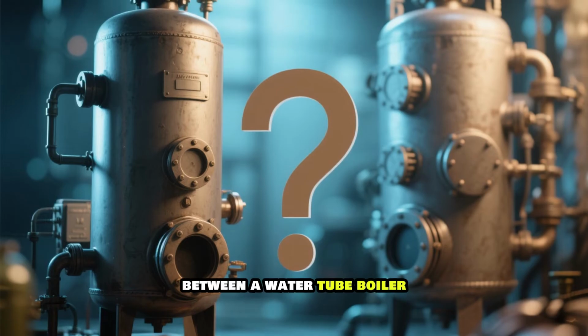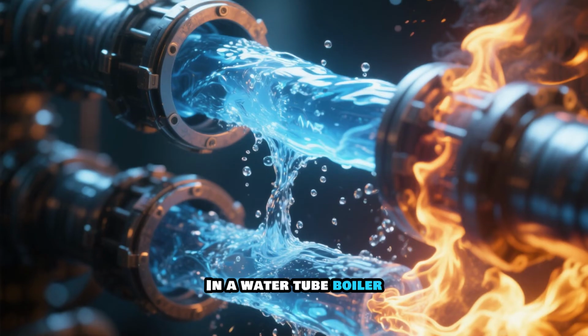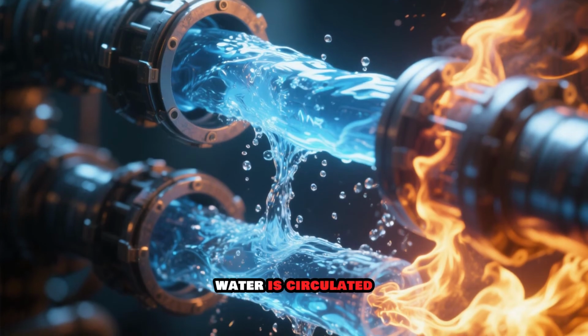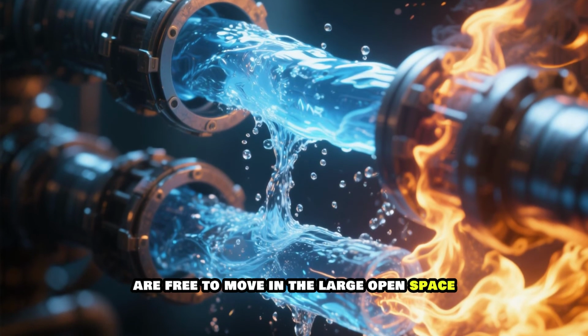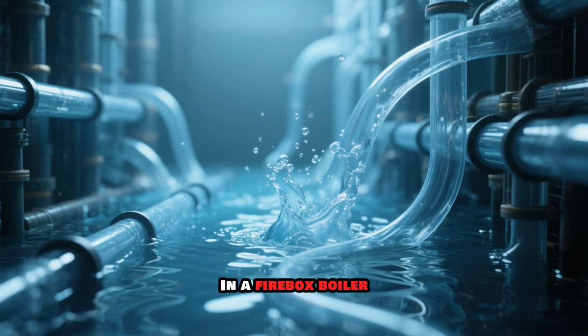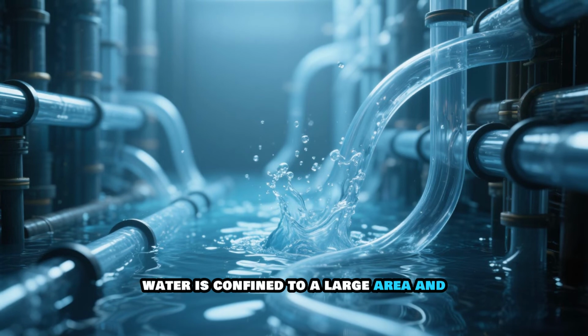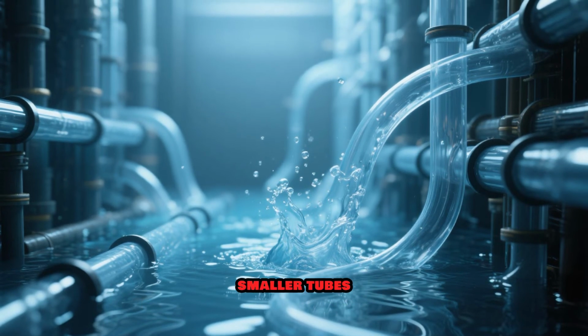What is the difference between a water tube boiler and a firebox boiler? In a water tube boiler, water is circulated through tubes, while the products of combustion are free to move in the large open space outside the tubes. In a firebox boiler, water is confined to a large area, and the gases pass through smaller tubes.